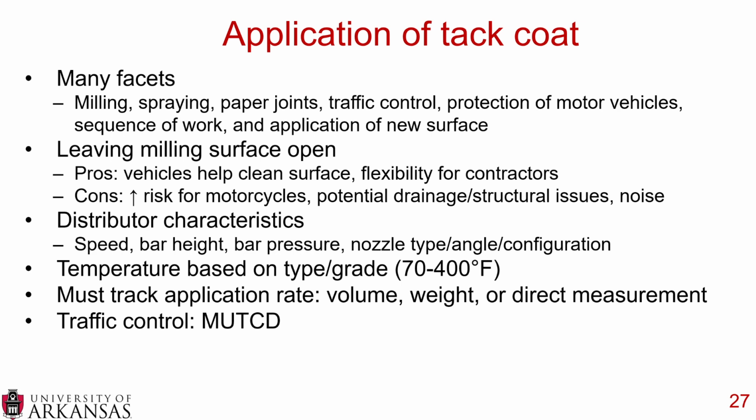You must track your application rate, so how much you're putting down. There's a lot of different ways you can do this. You can do it by volume of material being placed, you can do it by weight of material being placed, or you can directly measure it by taking a sample out of a nozzle with a little plastic container, or put a pad down on the road, a lot of different options there.